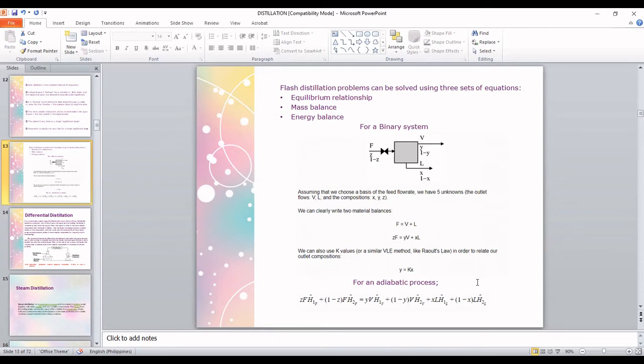this particular energy balance equation that is being used. But we will not be discussing it here anymore because, I will emphasize this, in distillation we normally only use overall material balance and component balance. In terms of overall material balance, as you could see here, if it's possible, I can show this bigger. Let me know if you can see it bigger. If you just do overall material balance, you will have only a single stream equated to the sum of the 2 leaving streams, the vapor and the liquid phases, in the case of your flash distillation.